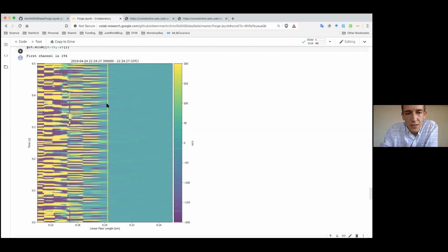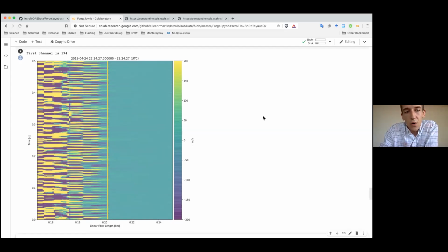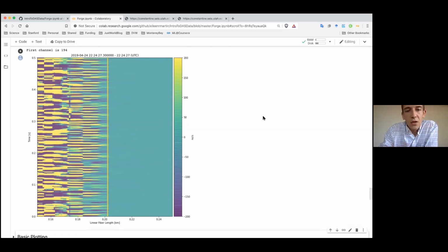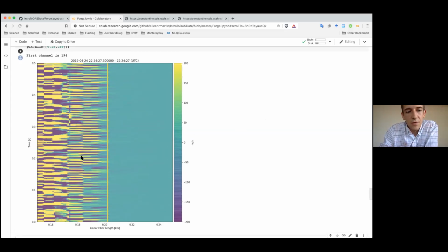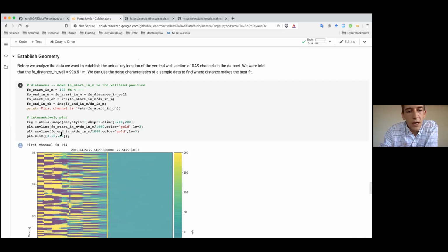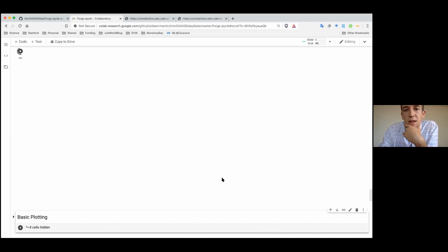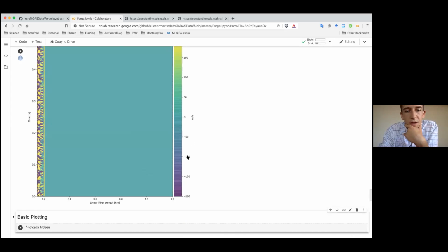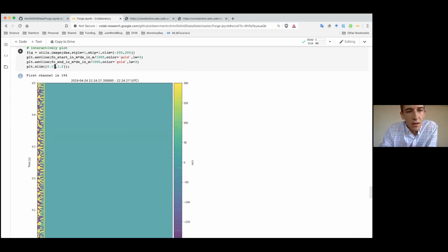So there's a certain amount of resolution that you actually have when you're doing tap tests. That's why oftentimes when you're recording a tap test survey, you'll try to ramp up the channel spacing to make it as fine as possible to look at these spacings. That seems pretty good, so we're going to say the first channel is at 194. If we go out to the end of this array, we'll see the other yellow line is down here at